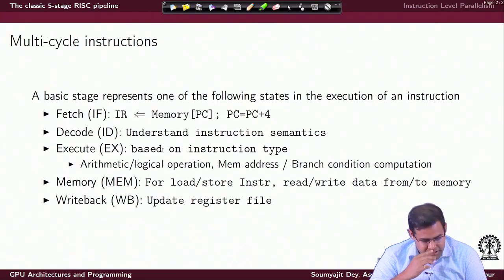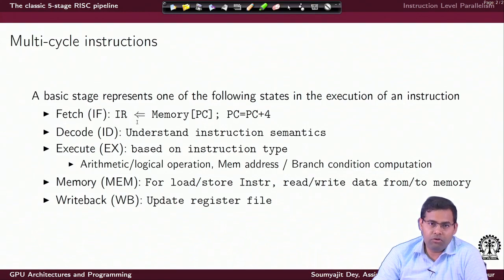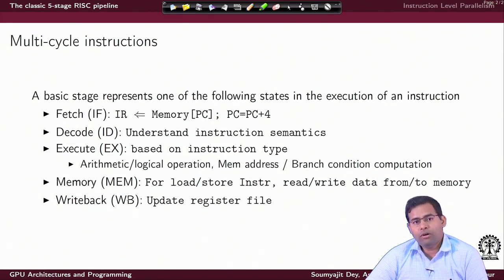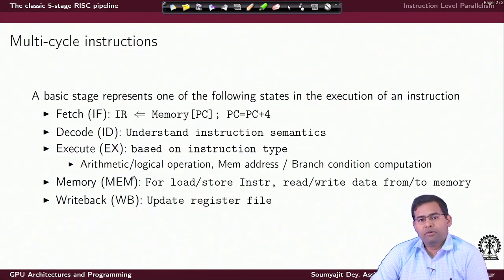Now, this execute stage has to be followed by another stage called the memory stage. What is this for? In case the instruction is a load or store type instruction, it needs to fetch data from a memory location, and that data has to be loaded into the register file. So, this fetching of data from the memory will be performed in this memory stage.